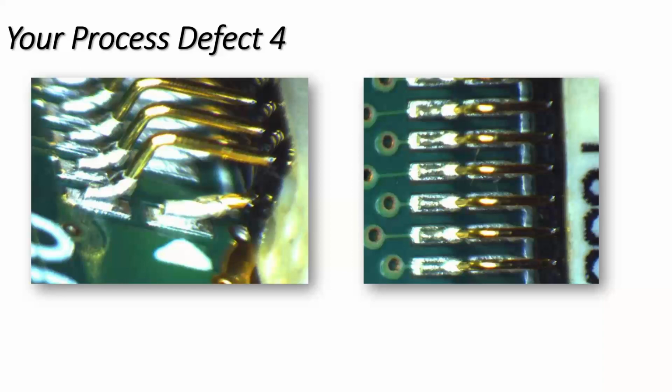Now, the first thing I would say is that obviously this is a specialist connector. This is not a standard connector. And ideally, the pins should be parallel to the surface of the pad. And in that particular case, you are less likely to draw the solder up the pin and away from the joint area, reducing the volume that is actually there. That's the sort of first thing.